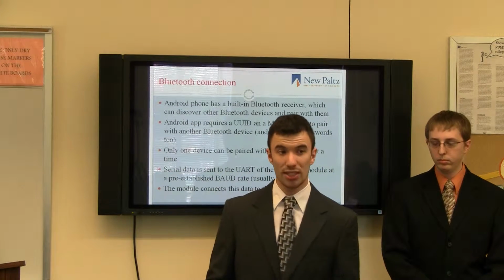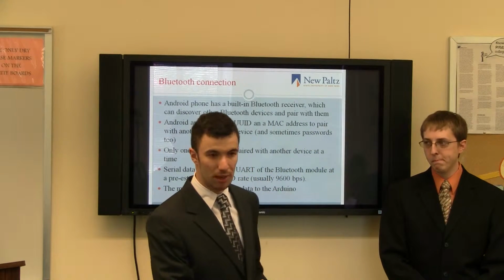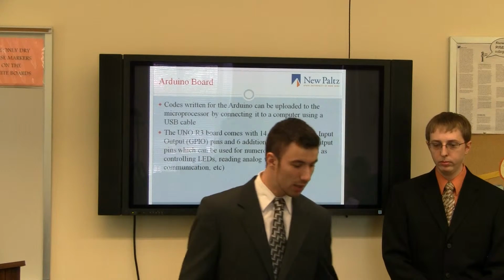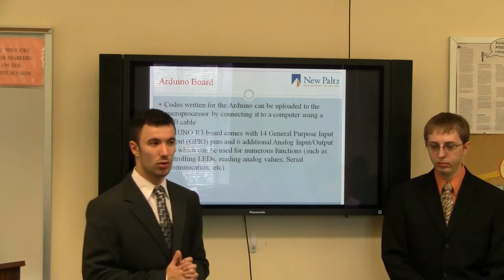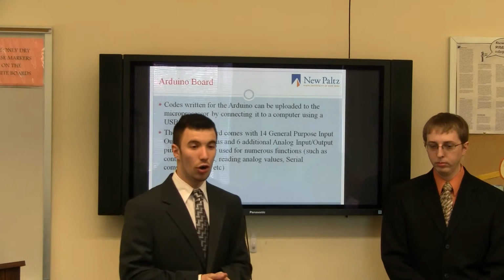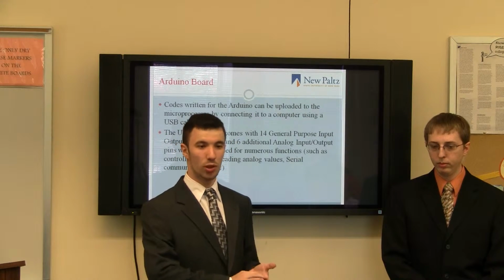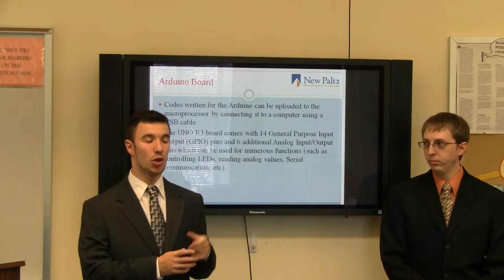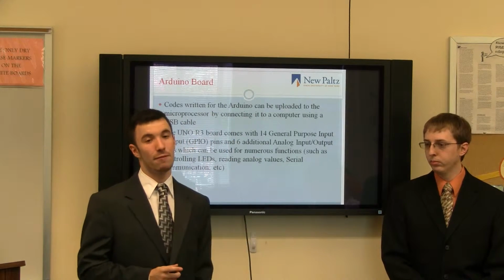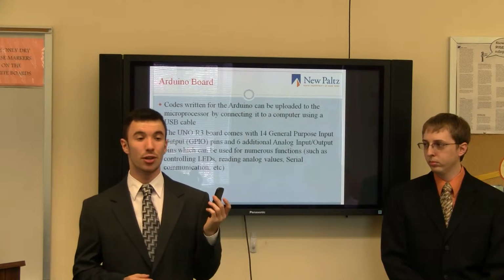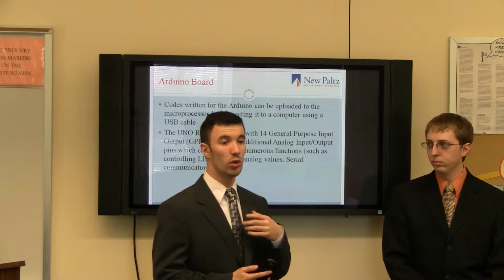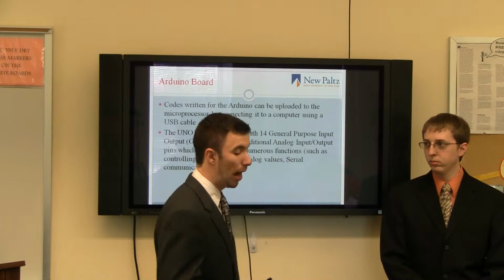This data we're going to send to an Arduino board, if I didn't mention that before, and that's going to take the Bluetooth and control it. So the Arduino board is going to have an uploaded Arduino sketch, which is some sort of code written in that language, and it's going to have a Bluetooth module connection to talk to the Android phone. So I could have my Android phone right here connecting to the Arduino board, which I left upstairs with the Bluetooth module, with no computer attachments, just power.